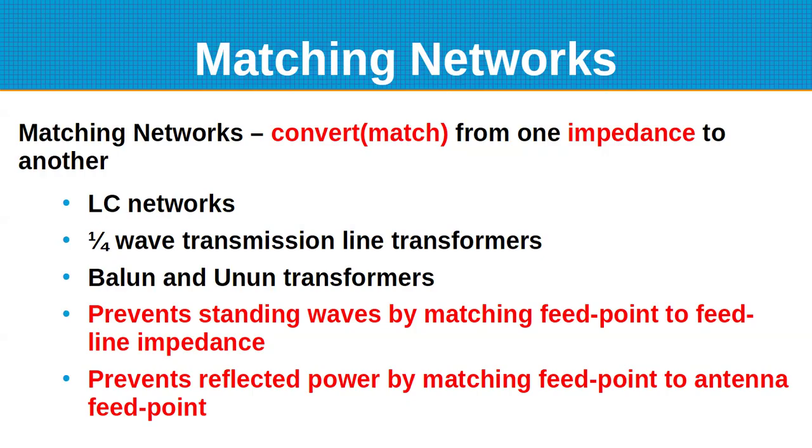Now in an auto tuner, it's basically the same thing, except it's done by a bunch of relays and separate capacitors and inductors. And the processor will just trial and error different combinations of capacitors and inductors to get the best match. And a lot of times, if it's quiet, you can actually hear it switching when it's trying to do that. You hear the little clicking.